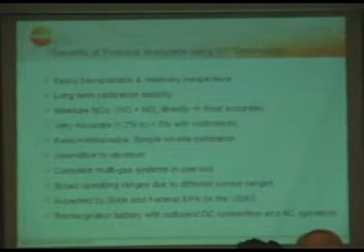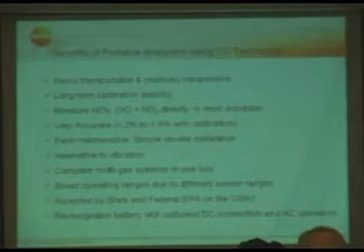Then you can measure NOx separately, like NO and NO2 directly, which is the most accurate reading because we have both parameters measured, and at the end we build the sum of NO and NO2 to have the real NOx reading.